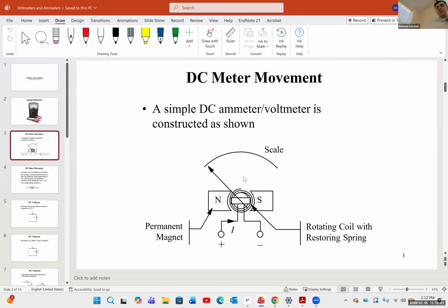Now, also with me, I brought another type, which is an older type. And you can see here, this one is an ohm meter. An ohm meter works like a voltmeter and an ammeter. It uses Ohm's law. You put a known voltage on a resistor, and then you measure the current, and using Ohm's law, you can determine its resistance. So you can see it shows the ohms.